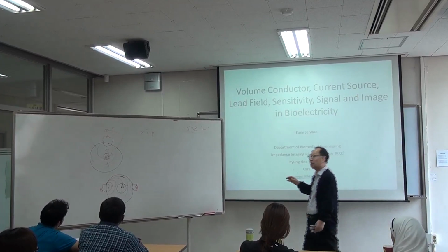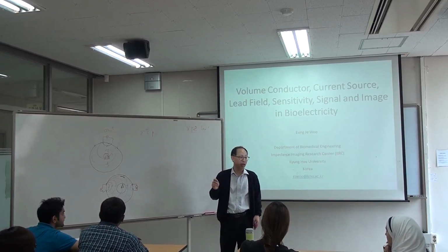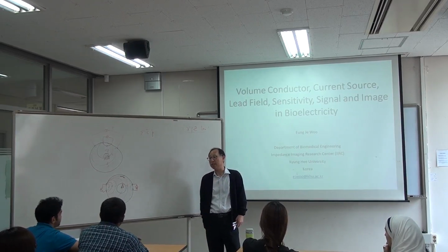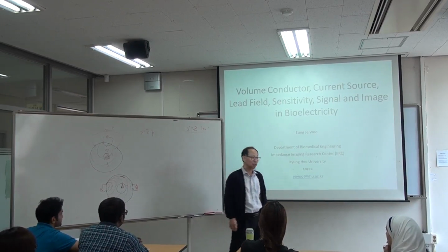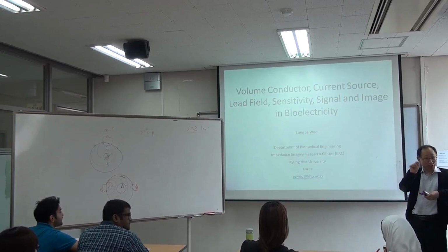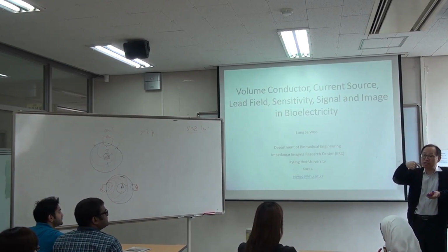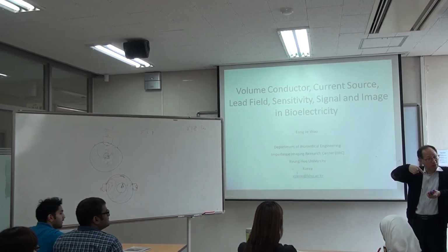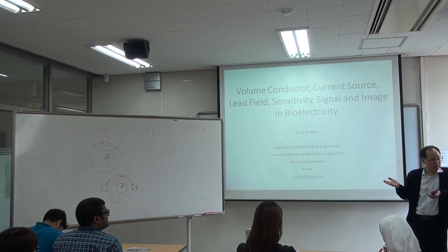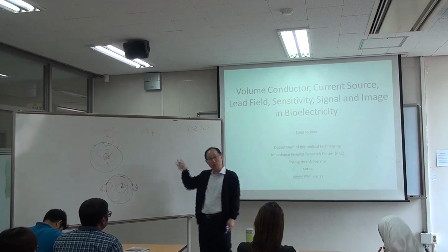From the knowledge of lead field theory, you should be able to design electrical configuration for all different kinds of biopotential measurement: ECG, EEG, EMG, EOG, whatever. What should you know? You should know where the internal current source produced by neuronal activity is, and the direction and magnitude of that equivalent dipole moment, in the heart, in the brain, or wherever.